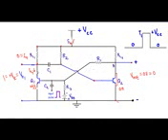That means the output voltage of the transistor Q1 will be at logic 1, and the output voltage of the transistor Q2 will be at logic 0, and this 1 is the stable state for this transistor Q1, and this 0 volt is the stable state for the transistor Q2. The output is stable at this 0 level. What does it mean?